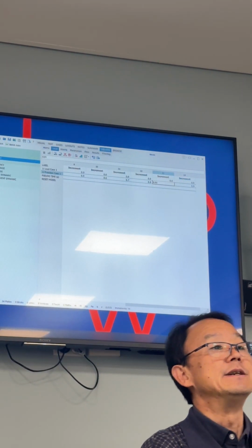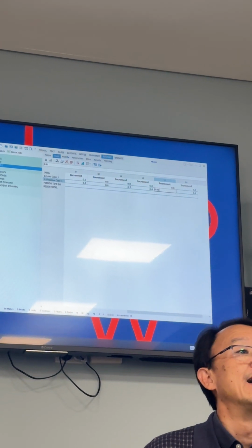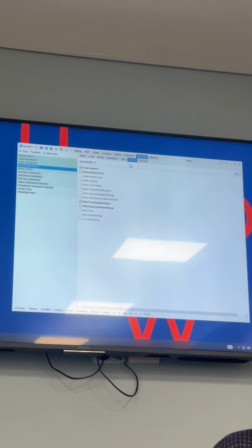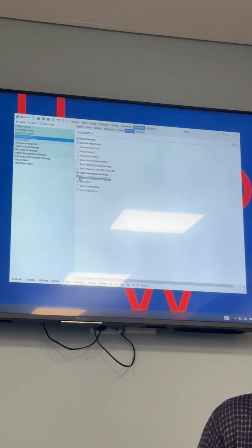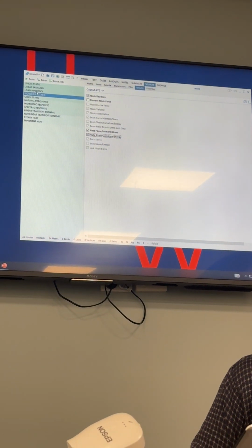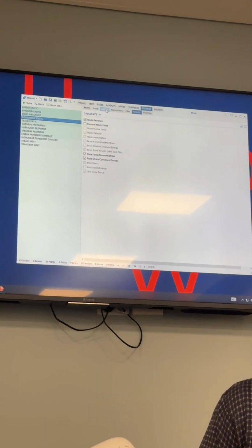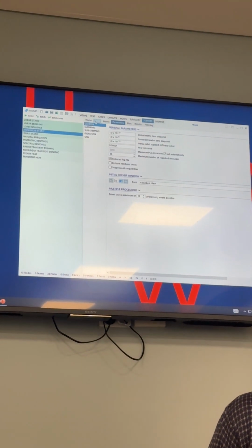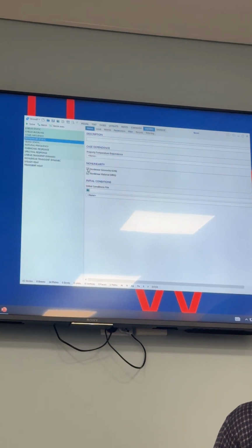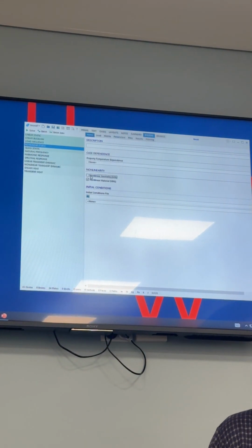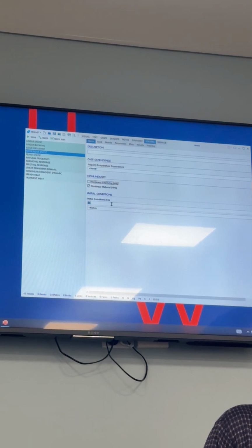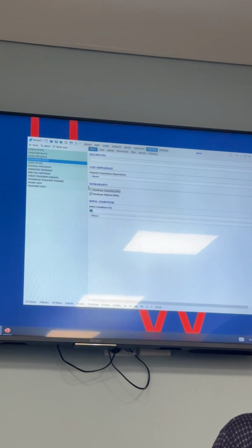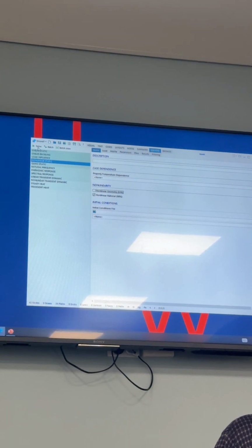Okay, you need to import the load, and you need to choose what result you want. Okay, in your shopping list, you want the plane strain as well. Now, I think I missed a point. For nonlinear static material property, you need to always tick off nonlinear geometry. It's too complicated. Only choose nonlinear material, okay? Okay. When you have done this one, you could solve it.